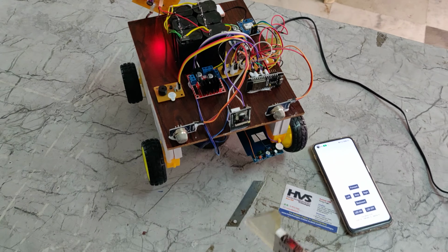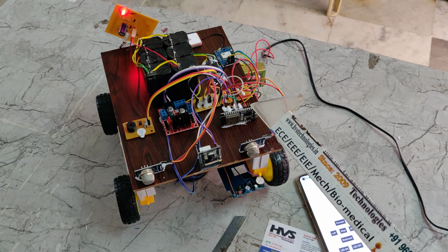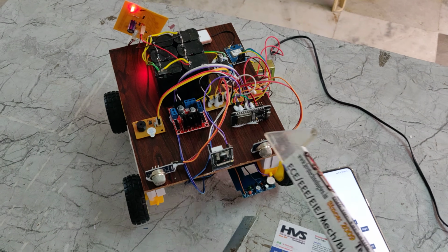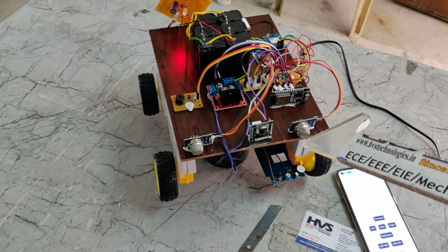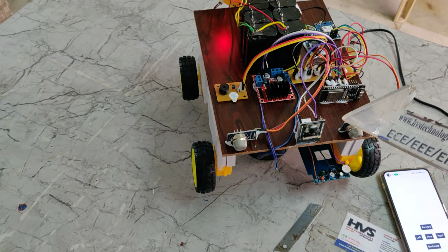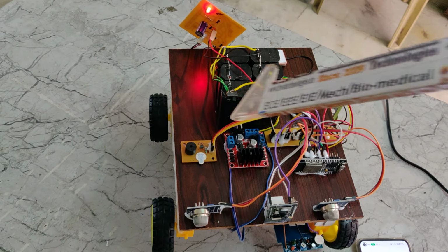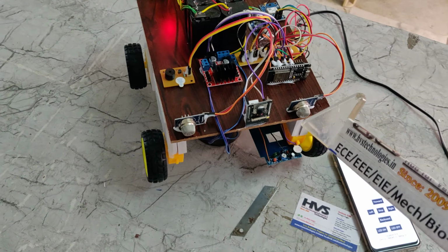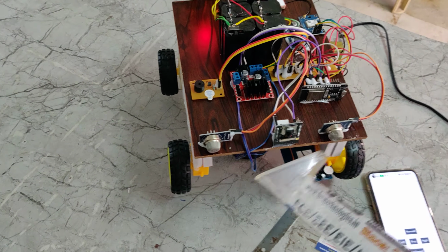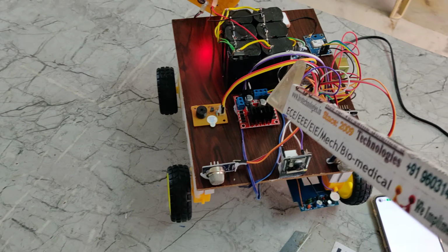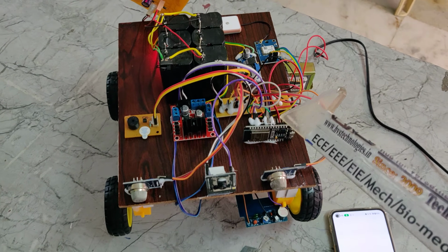So here are the main features, as we discussed. The sensor part and robot movement part are interfaced to the ESP32. The gas, smoke, and metal sensors are interfaced to the ESP32: smoke sensor at pin number 18, gas at 39, metal at 36, and the buzzer for audible alert. Whenever a threat is detected, you will get the audible alert through the buzzer, which is interfaced to the 23rd pin. The GPS is at the transmit and receive pins of our ESP32, and pins 25, 26, 27, 14 are for the L298 motor driver, and the ESP32 camera is interfaced to the transmitter pin and receiving pin.